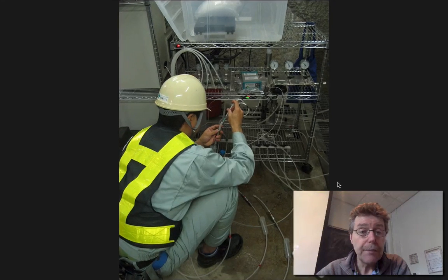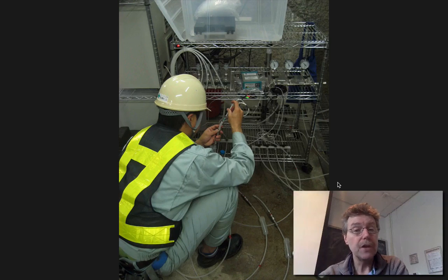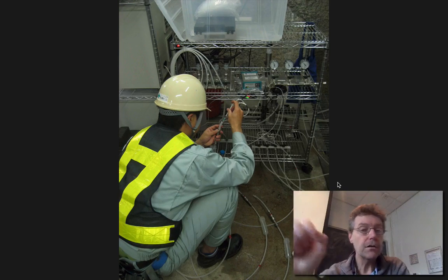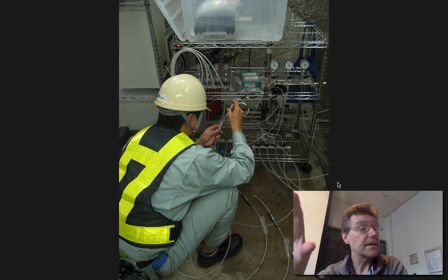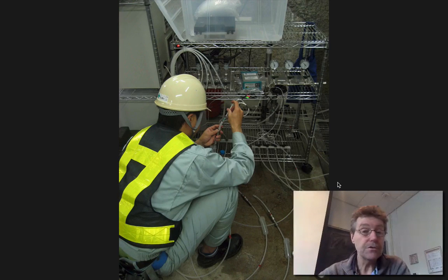And this is just a bank of sampling locations, a whole bunch of piezometers, well bores that go in from the tunnel into the rock. You pump in, say, a tracer, and then you measure the arrival of that tracer at a bunch of locations, mainly by doing syringe sampling on capillary tubes to be able to pull stuff back from those sampling locations.